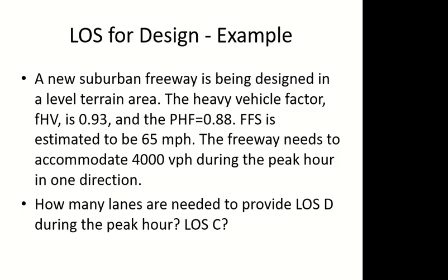As I mentioned previously in these questions, the first thing you look for is free flow speed. If it is not given, you will calculate it. Fortunately, it is given here, and there are no adjustment conditions given here. No work zone, weather, driver familiarity, or incidents. So we don't have to worry about the adjustment factor here. We can use the graphs directly then. If you remember, I showed you the graphs. One of the free flow speeds on the graphs is 65. We can use it.